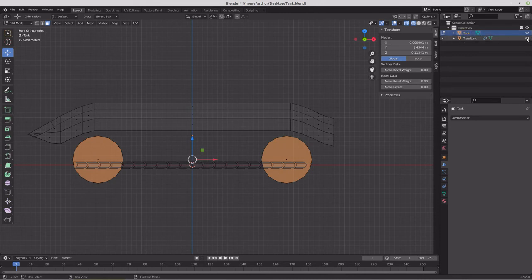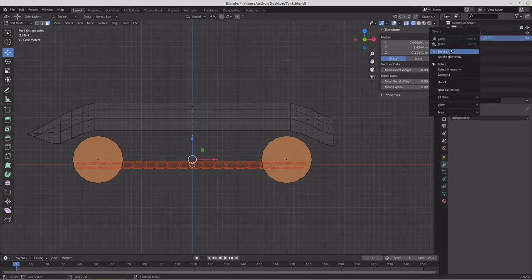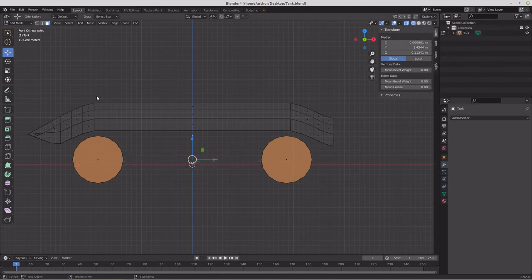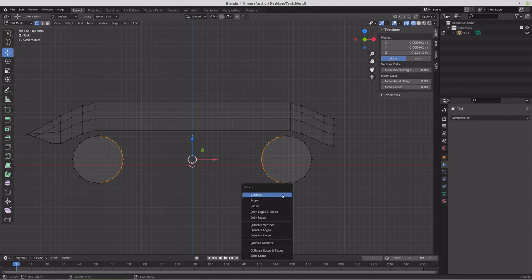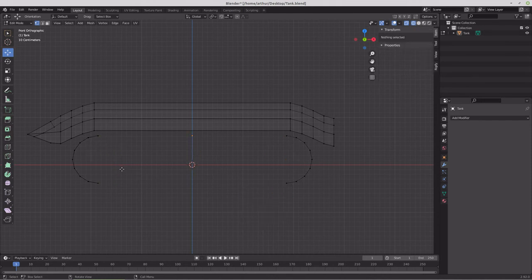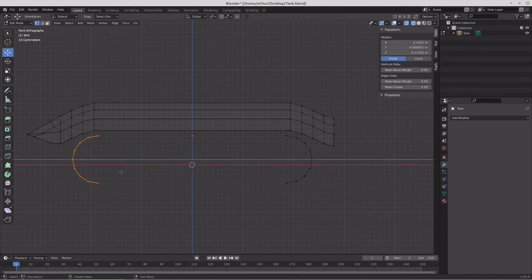The tank tread is no longer needed, and this is a branch file, so we have the tank tread saved in a different working file. We'll go to vertices, and we'll box select this half of all of those cylinders. We'll delete the vertices. We'll circle select over here, extrude,